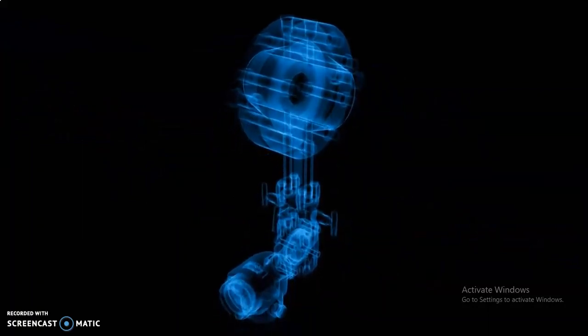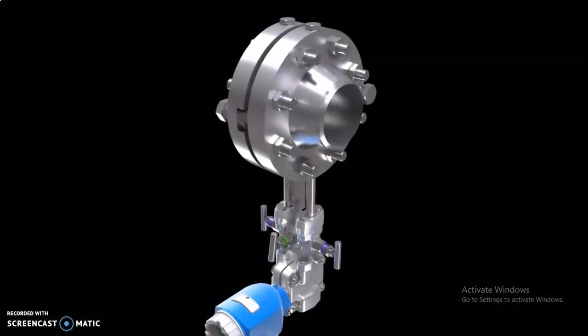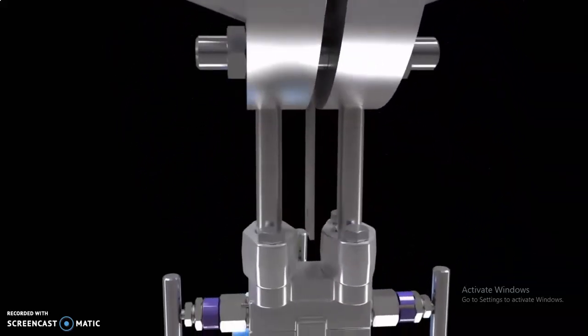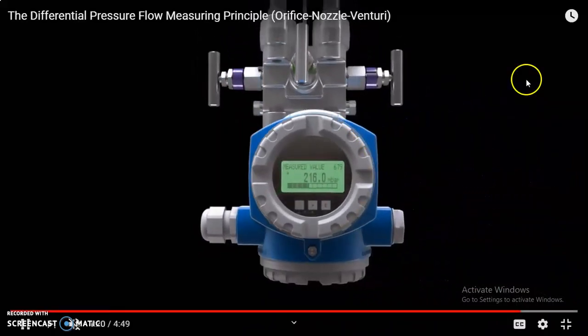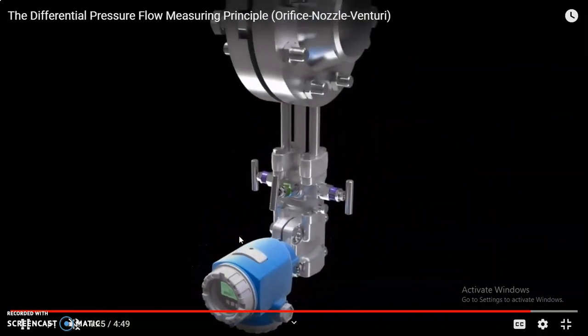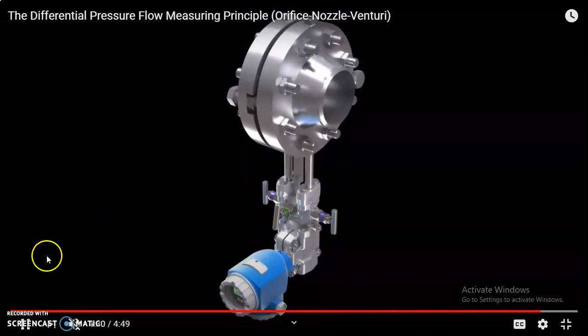This is how the pressure difference is measured via this orifice meter. The minimum cross-sectional area of the fluid obtained downstream from the orifice edge is called the vena contracta. So this is how the construction of the orifice flow meter looks. In the panel, we can identify the manufacturer value and the readings, and these are all the adjustments they have made. So I think you will understand.